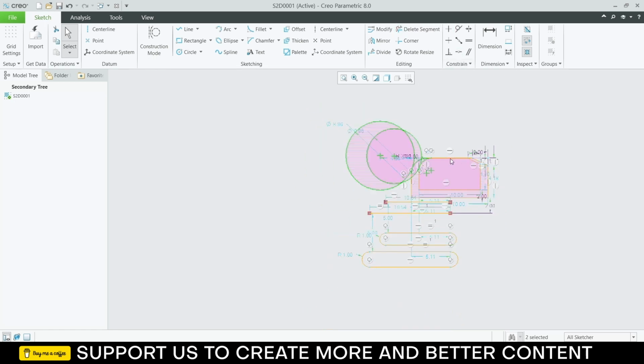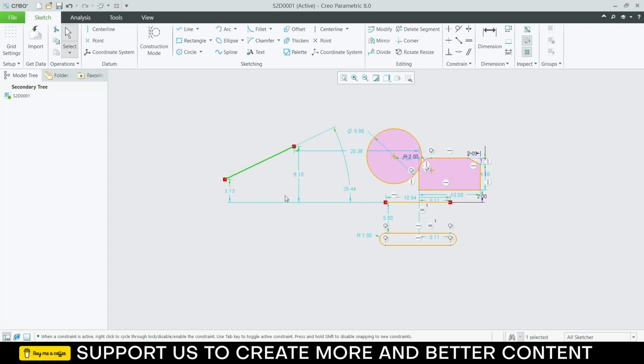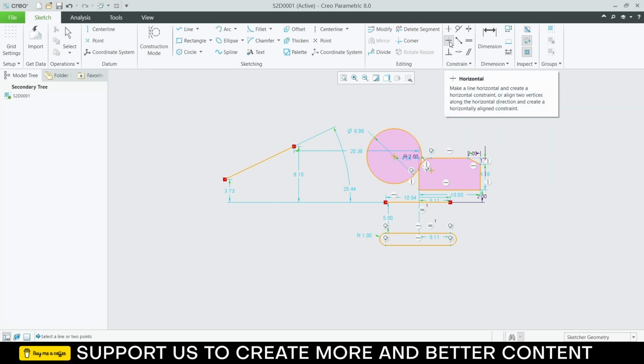Similarly, there are plenty of other relations. For example, if I draw a line like this, and I want to make it a straight line, I can select this line and make it horizontal, but I am not able to do it. Why? Because of these dimensions. There is a constraint here because of this dimension constraint. So what I can do is click on dimension, select this, delete, make it 0.